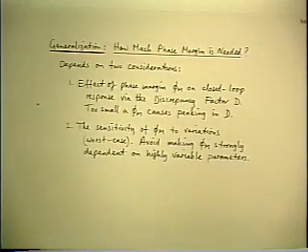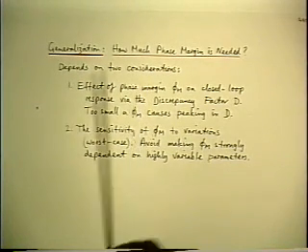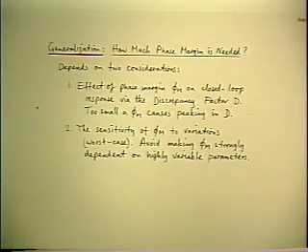So, to summarize this point now, we started out by posing the question, how much phase margin is needed? And we decided pretty quickly it wasn't the right question. The right question is, what is the relationship between phase margin and closed loop response? Because that's what has to meet the specifications.